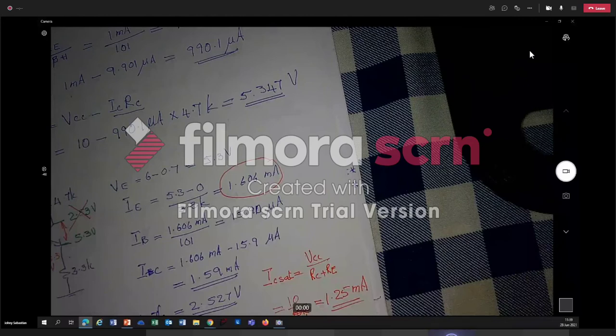It can be any value; if it is more than 0.3, then there is no problem. Then it is saturation. For the test, of course, there is going to be a part of the question where you work out the maximum collector current possible in this circuit, or maybe a question like: decide if this BJT is active, cutoff or saturation. Usually, if it is saturation, there will be a supplementary question like calculate IC sat.